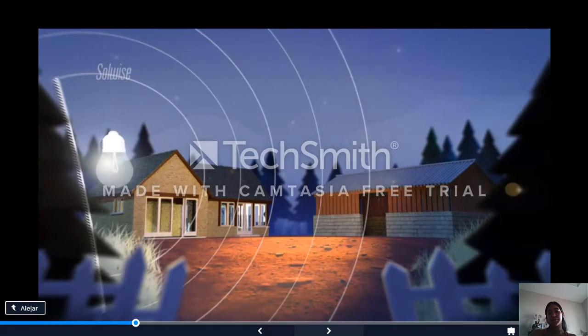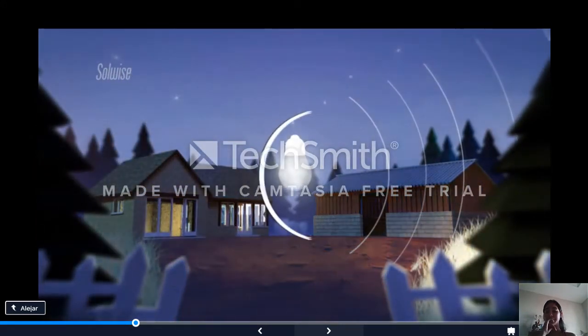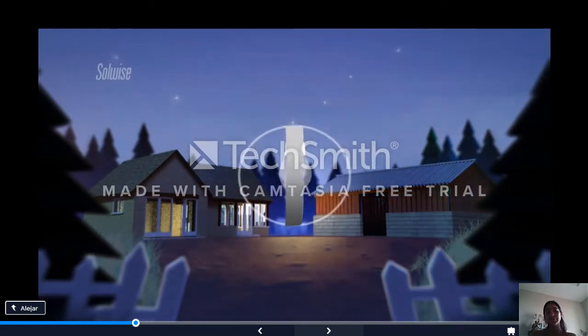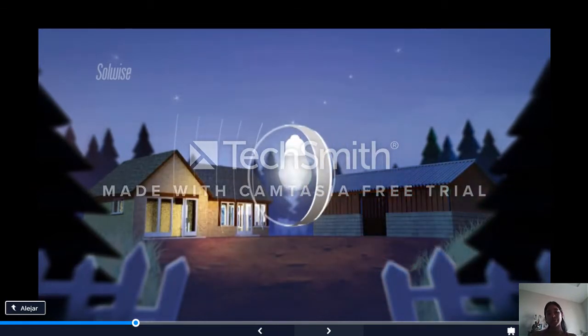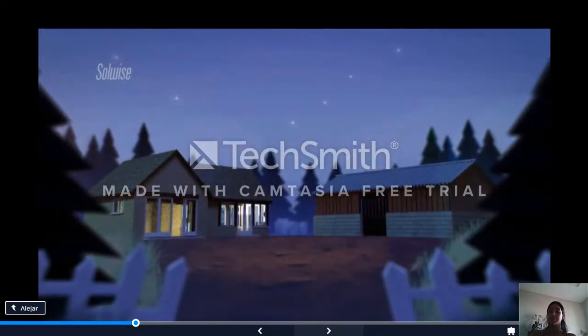If we need an even brighter beam of light, we could use a curved or dish-shaped mirror. This would provide a bright but narrow beam of light. So what have we learnt? We have seen that changes to an antenna do not increase its power, but we can increase its effective output power by focusing the radiated signal. In effect, gain is achieved by focusing the antenna.